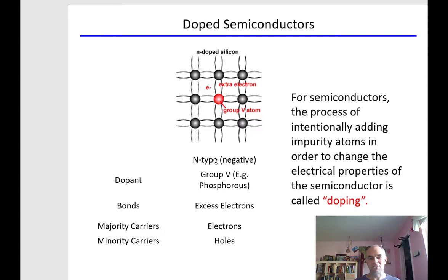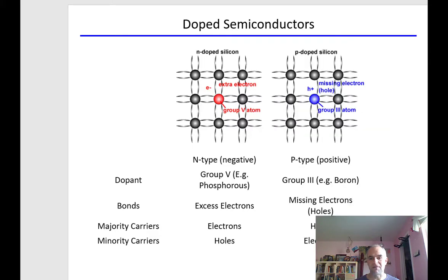And then you have, as I mentioned earlier in the previous video, a p-type material as well. And the p-type material, that is typically boron, will have 3 valence electrons. And so in the p-type material, you have a hole here. Now note that this is still neutral and that's still neutral, but you have an excess of free electrons here, and an excess of free holes here, or absences of electrons.